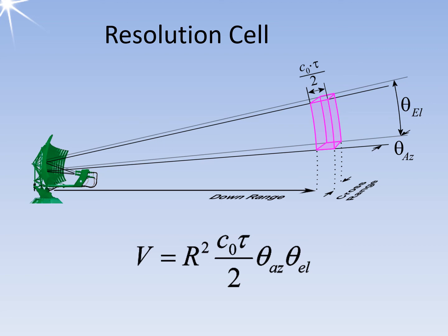A comparable significance for a surveillance radar arises when the resolution cell is filled with passive interference. This case can occur with the so-called chaff. Chaff is artificially deployed clouds of small dipoles, which slowly sink to the ground and generate an area of strong echo signals, behind which attack aircraft can hide. However, weather interference can also occur at higher frequencies. For example, a mobile speed camera will not work in heavy rain. But there are other methods of speed measurement than just radar.